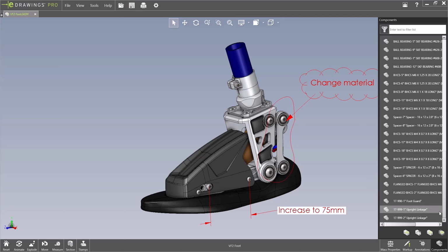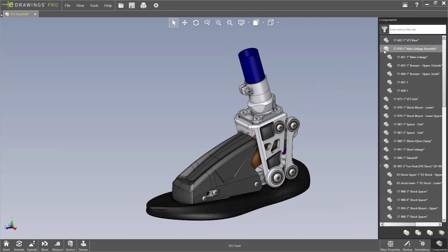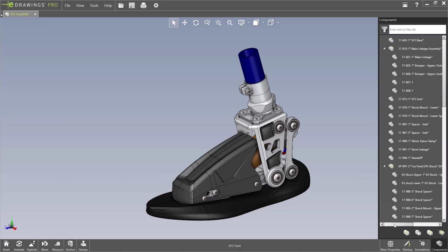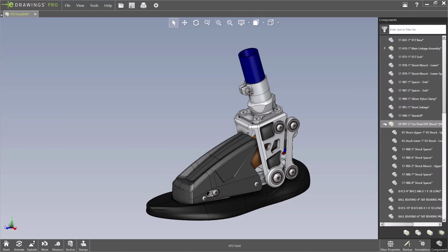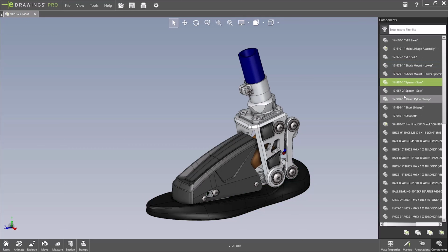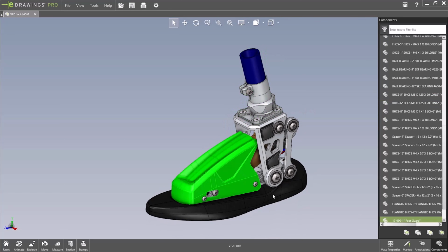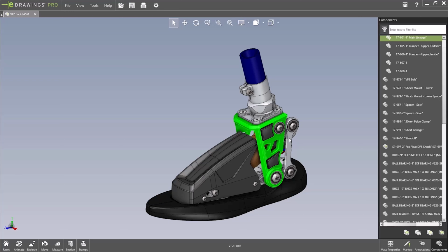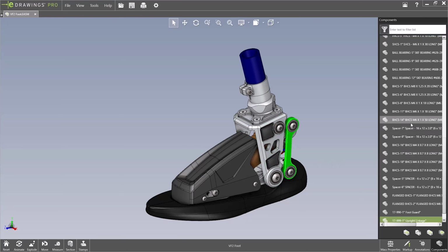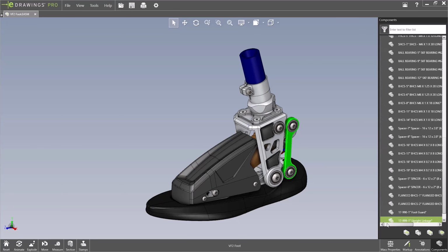And the last one is components. So in this case, this is an assembly. So we have a full list of the components that make that assembly up with the structure as it was in SOLIDWORKS. This supports full cross highlighting. So if we select any of these objects in the tree, the model window highlights the corresponding parts as well. And this works the other way as well. So we highlight the parts, the tree is enabled. Now this allows us to also view any file names and configuration names and descriptions that would have been stored in SOLIDWORKS.